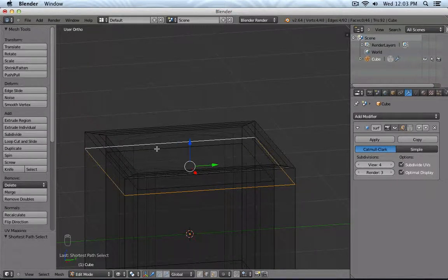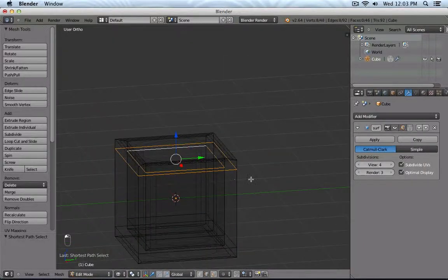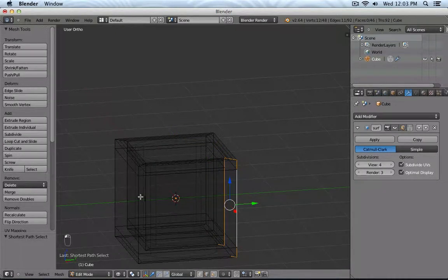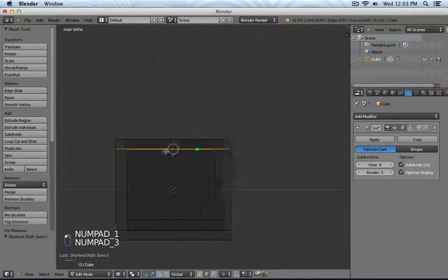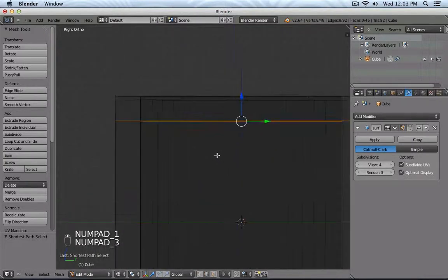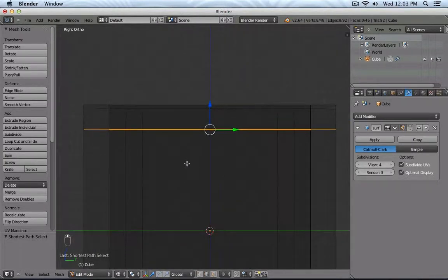And pressing Shift and Alt and clicking on this edge selects the next ring and adds it to my selection. If I, for example, click here, you see that everywhere it adds a logical loop cut that is physically present.